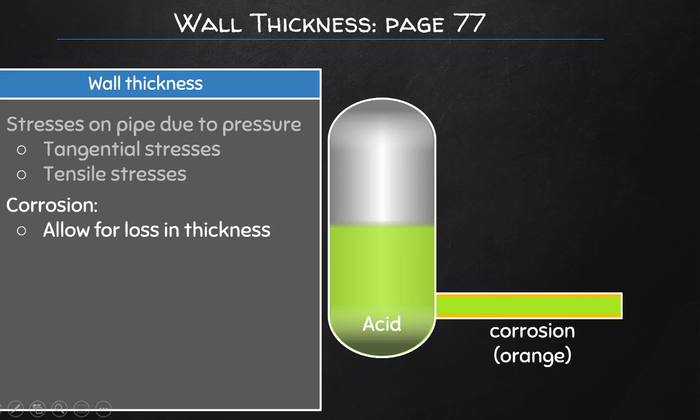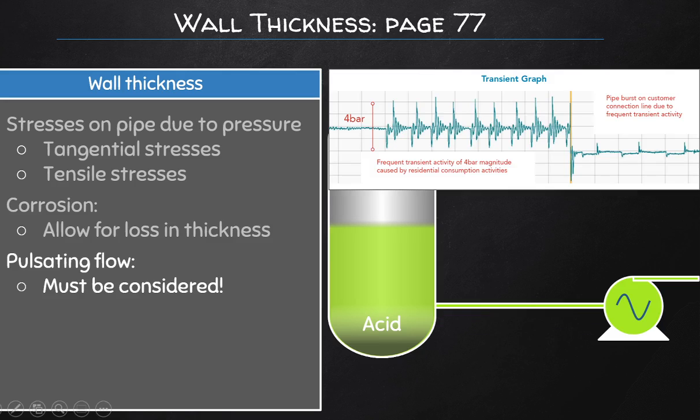Now, another source of concern is something called pulsating flow. Okay, so it is how the fluid movers themselves induce vibrations in the fluid that may elevate or depress pressures. So we're not just talking about high pressure but also low pressure, because this can form implosions of equipment. But also velocities, of course, and this happens in such a way that the integrity of the pipeline and equipment is tested to the point of failure.